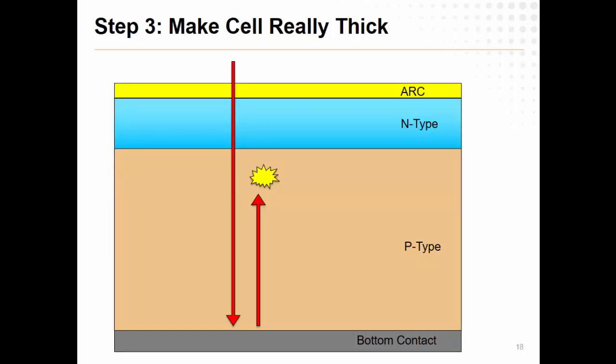I can make my solar cell really thick, which is why that other one's like 400 microns thick, as you saw. If I just have this thing infinitely thick, eventually that photon's going to get captured sooner or later. But you can't make it too thick, because if it's miles thick, again, those electrons and holes have to migrate somewhere, so you can't push that too far.